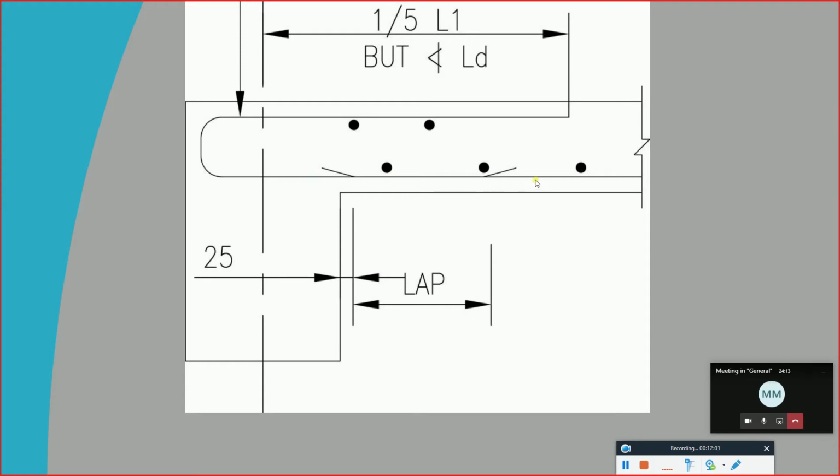You can see that there is an intersection point between this reinforcement and the second reinforcement. Okay, so this reinforcement goes from here to here, and the second one starts from here and goes to the top. It means that this portion is an intersection area, between the reinforcement at the bottom and the reinforcement at the top. And this we are calling lapping. That's why it's written for you that this is going to be lapping.